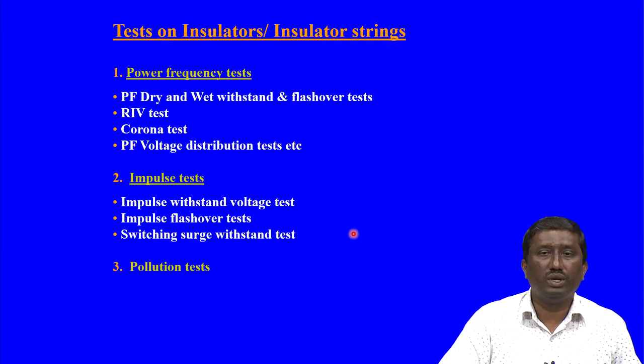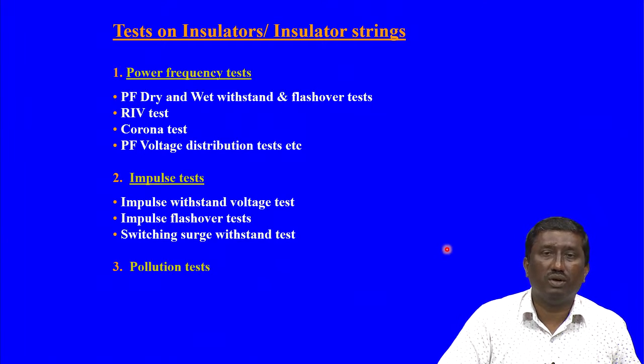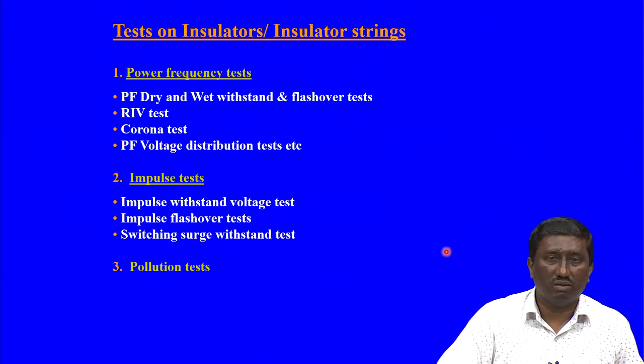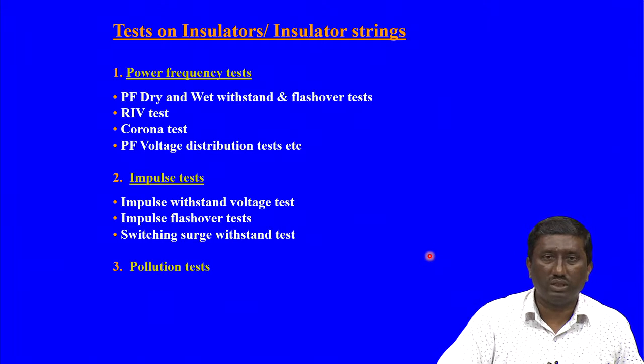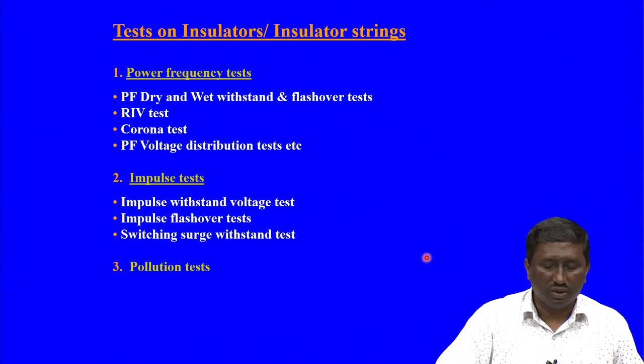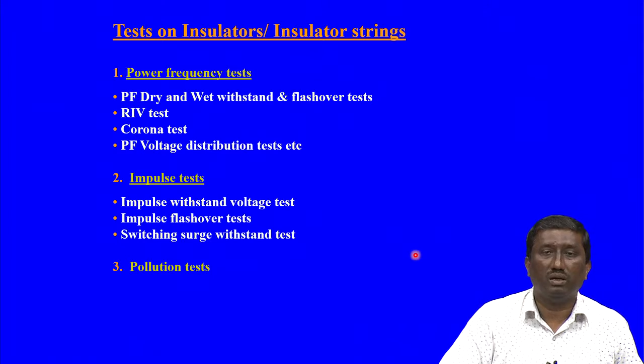And again impulse flashover. So, if impulse withstand is what voltage level it withstands, then flashover is when it could flash over, indicating the healthiness of an insulation when the voltage level goes on increasing. So, the flashover estimation also has to be done for the severe effect in case higher voltages are seen by the equipment, the flashover should not happen. But this would give an estimation of how the insulation flashes over and what is the level which could be compared with the withstand and the flashover.